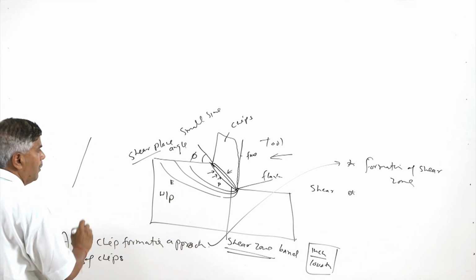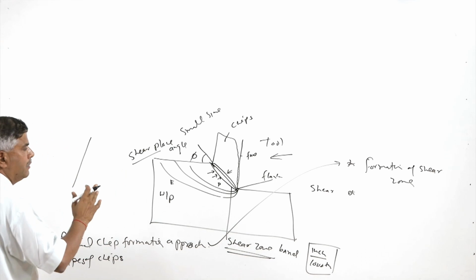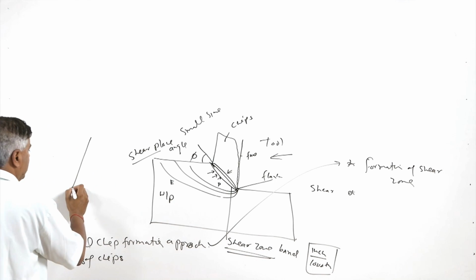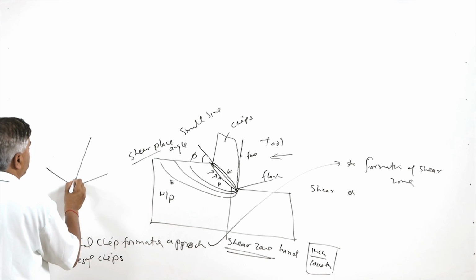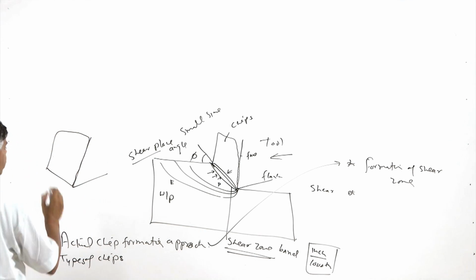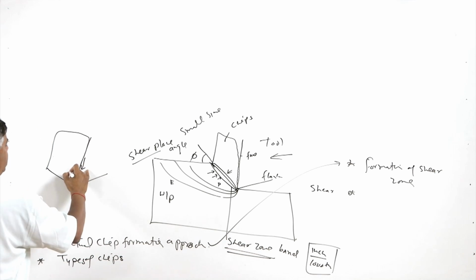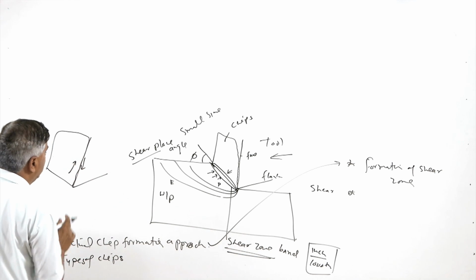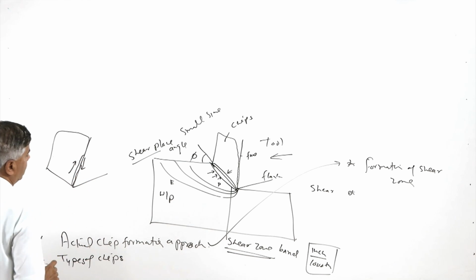So this is the shear which is facilitating the removal of the material in the form of the chip from the workpiece. While the material after getting removed, under pressure it passes through the face of the tool like this. Since there is friction during the movement of the chips over the face of the tool under pressure, some kind of deformation is also observed along this zone.